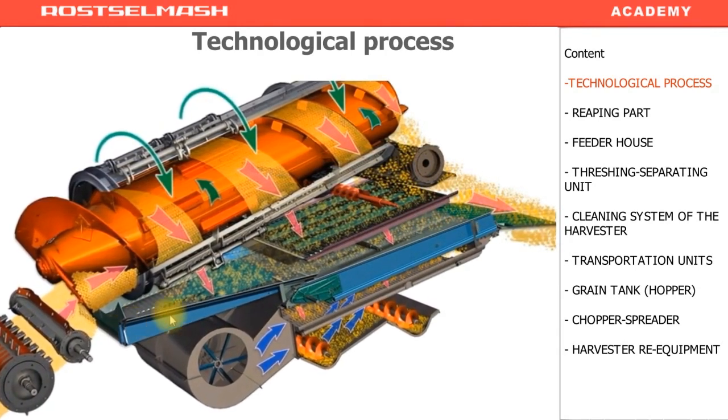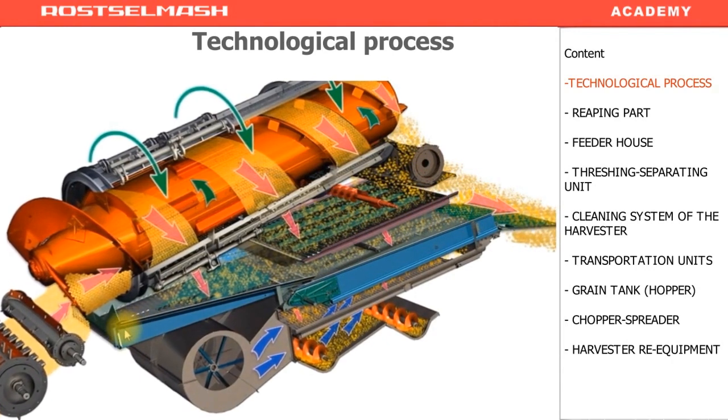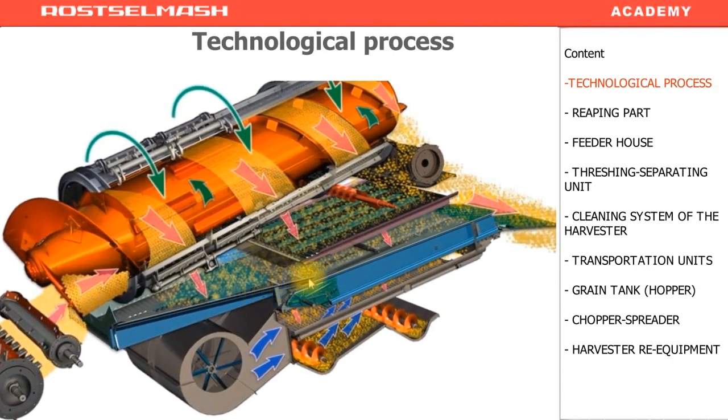Everything that falls on the shaker pan, due to in and out movement, is transported to the pre-sieve. On the pre-sieve, the separation process occurs. Clean grain is spilled on the lower sieve. In this area, a flow of air starts cleaning the mass.